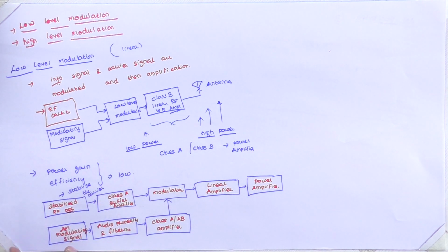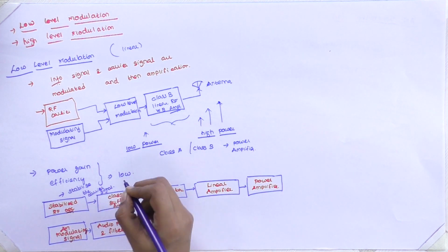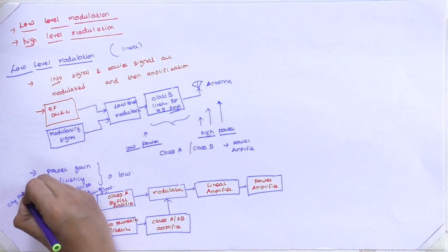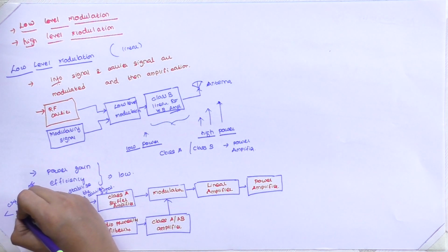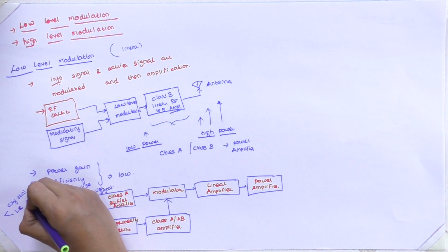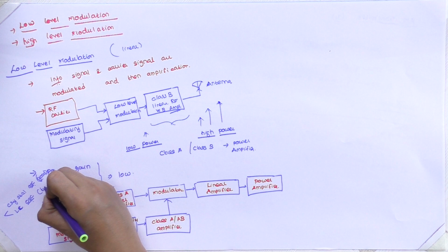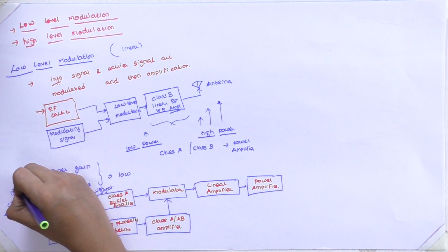In order to avoid frequency drift in the carrier signal. We can employ a crystal oscillator. Also we can employ an LC oscillator. But a crystal oscillator will always provide good stability, while an LC oscillator provides weaker stability.